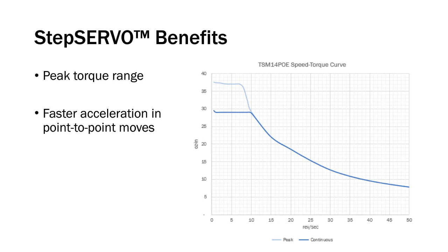Not at this time, no. Like a traditional servo, when you go into the tuning software, we guide you through it. You select base tuning parameters for the motor, and in this case, the tuning parameters are kind of baked in because the motor and the drive know each other, so to speak, because they're integrated. You set in a load inertia, and then the default parameters for tuning are set for you. But it's not what I would call a traditional auto-tuning function.